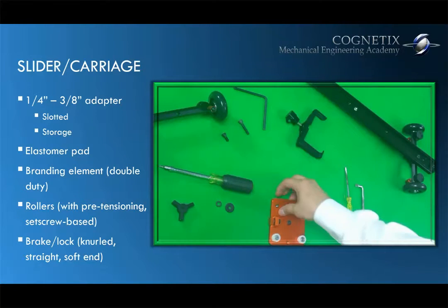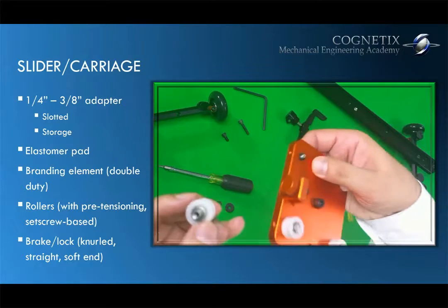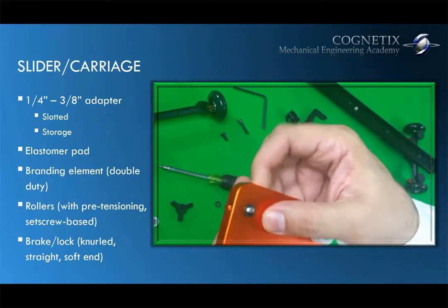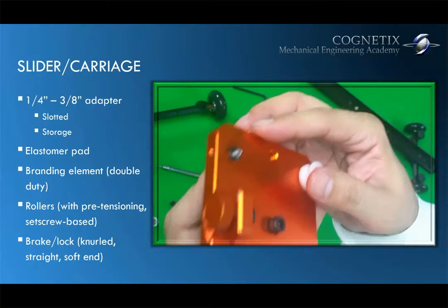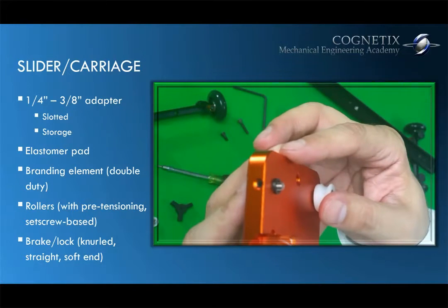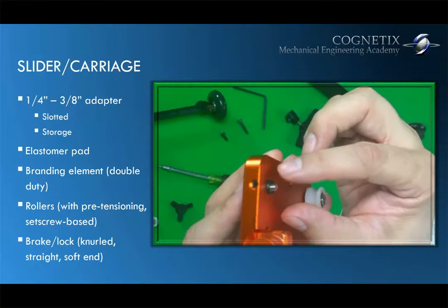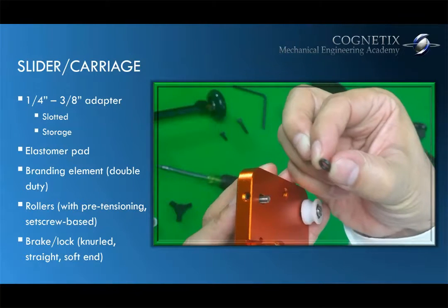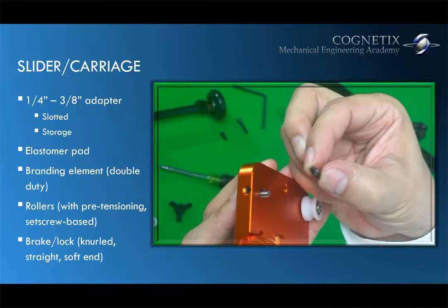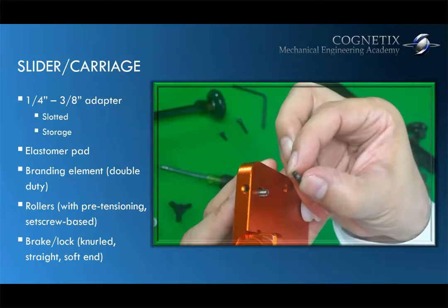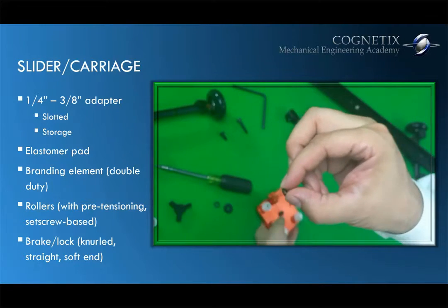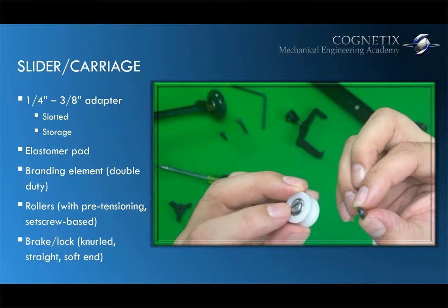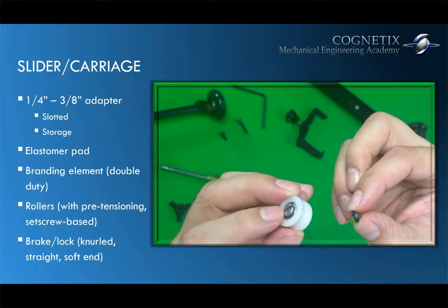So when we look over here at the other end of this axle design, put the roller down. What do we have here? Yes, as you can see, there's a washer. This washer right here is sized to contact the inner race of the ball bearing and enable proper function. So putting this down again, the head of the screw on this side contacts the inner race and locks it in position.